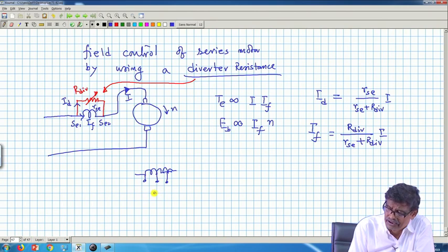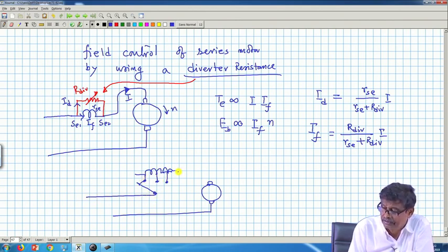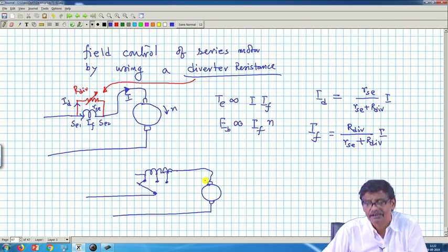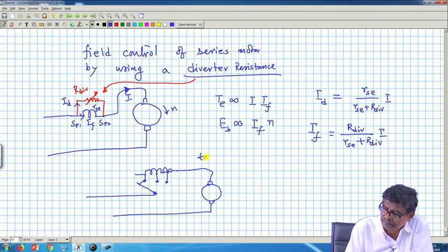and you can... this is not a very popular method, because you have to make and break the circuit. Your supply comes here, field winding, then armature. You can vary the number of turns of the field circuit, tap field, I am just mentioning. I have mentioned it in my note also.